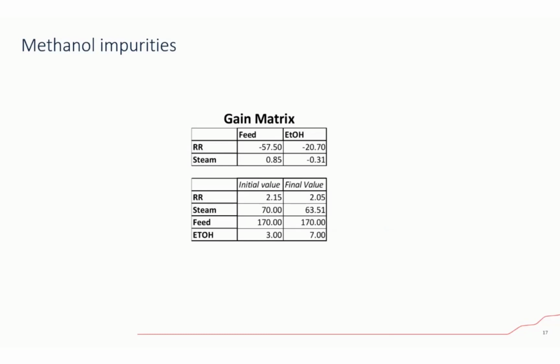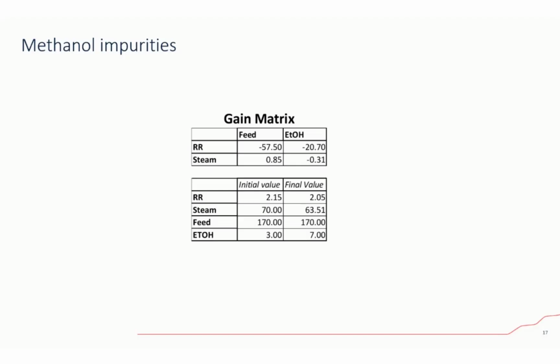But APC runs every minute, a whole other order of magnitude in terms of how fast it responds. So if you want the APC to do a job that you could do with a PID control, you will most likely not get the same performance, right?